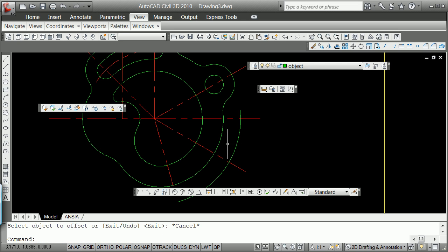And now I have two circles that are centered there. The circles' radii are 0.41. Circle at the intersection of here with a radius of 0.41. We have one circle. Might as well left click, spacebar, C for copy, to the intersection there. So we've got two of those circles.